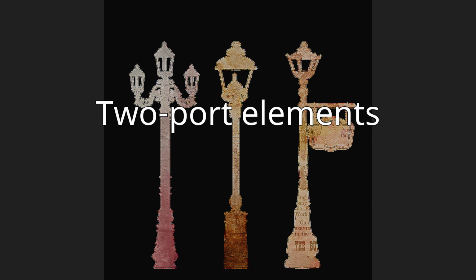It is not essential, however, to have both the transformer and gyrator. Two gyrators in cascade are equivalent to a transformer, but the transformer is usually retained for convenience. Introduction of the gyrator also makes either capacitance or inductance non-essential, since a gyrator terminated with one of these at port 2 will be equivalent to the other at port 1. However, transformer, capacitance, and inductance are normally retained in analysis because they are the ideal properties of the basic physical components transformer, inductor, and capacitor, whereas a practical gyrator must be constructed as an active circuit.